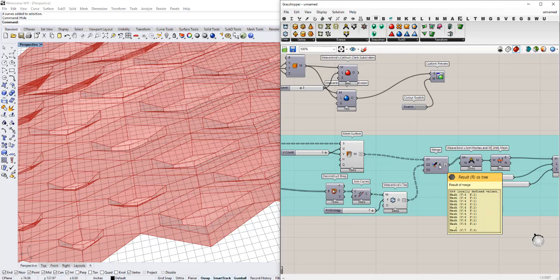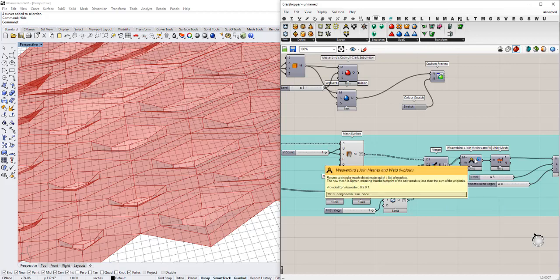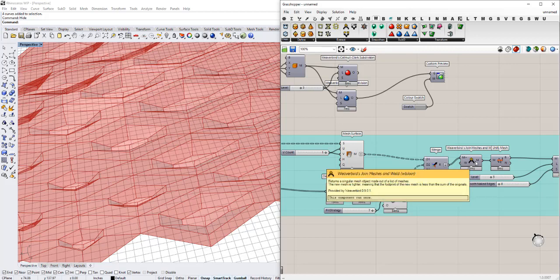Now, if I want to stitch those back together, if I were to smooth out all these and subdivide them, each individual face right now is a single mesh. So the smoothing between those would not really happen. I want to create a single mesh from that so that smoothing works. And so I'll need to join the mesh together and what's called welding. So right now, each corner point is not a single vertice that's shared with all of these. Each one has a duplicate vertice on top of itself for this face and for the other faces that are using that.